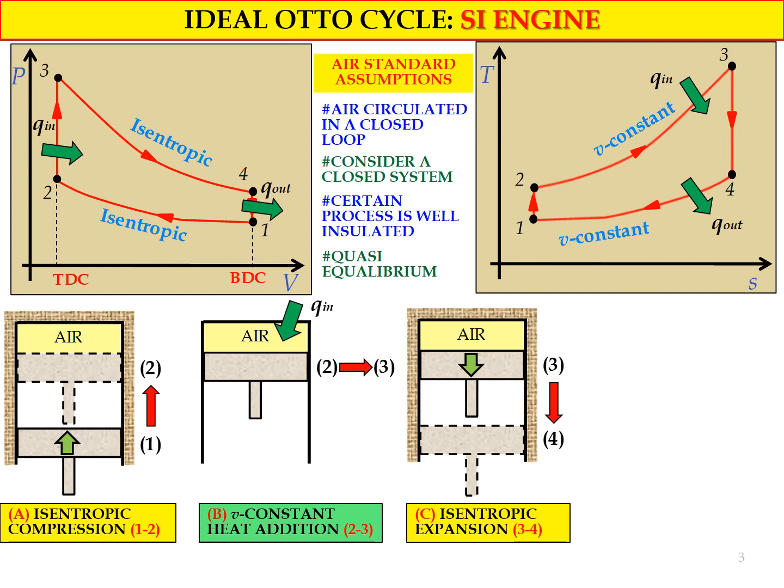So the piston will move downward, the volume will increase, and the temperature and also the pressure will reduce. So we have insulator surrounding the cylinder because the process does not involve any Q in and Q out during the process. Okay, because we do not allow any heat transfer during the isentropic expansion process.